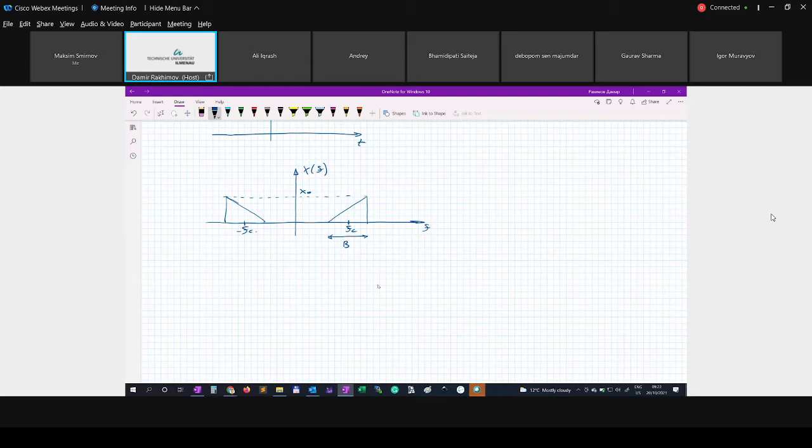Okay, and now we need to perform the band pass to low pass transformation. I will just show you the answer. We can do all these steps on the same plot above. Here we should get our spectrum in the low pass range, at the origin, and again, we perform the transformation with respect to carrier frequency fc. First step, we cut the negative frequencies. We just remove them.